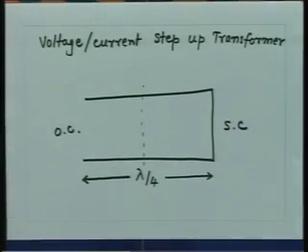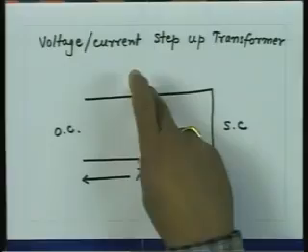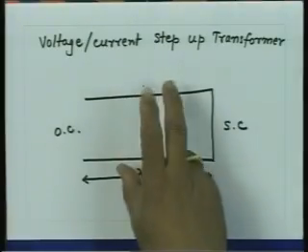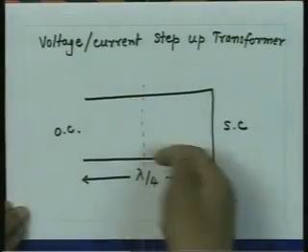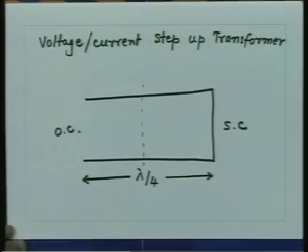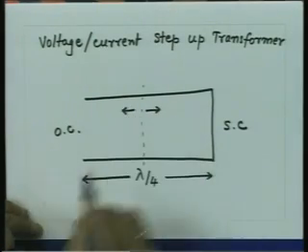Since the standing waves are not yet set up and the voltage is just getting induced inside the transmission line, this voltage does not see any impedance other than the characteristic impedance of the line. So, as soon as the voltage gets induced, it sends two travelling waves to both sides, because it sees as if the energy is supplied to the characteristic impedance of these two transmission lines. Essentially, two equal amplitude waves are sent from this location.